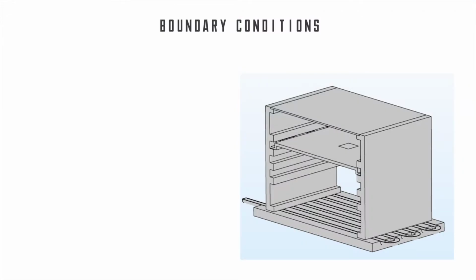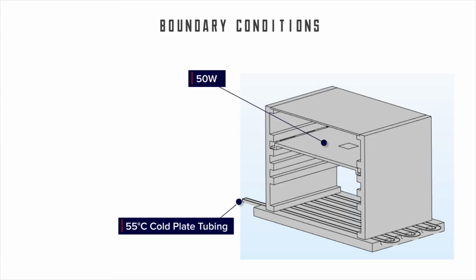In this example, the ultimate cooling is provided by a liquid cold plate along the base of the chassis, which runs fluid at 55 degrees C. The electronics board is generating 50 watts concentrated near its center and has additional components totaling 50 watts distributed across the board. To successfully reject the waste heat to the liquid-cooled base, the heat must conduct from the components to